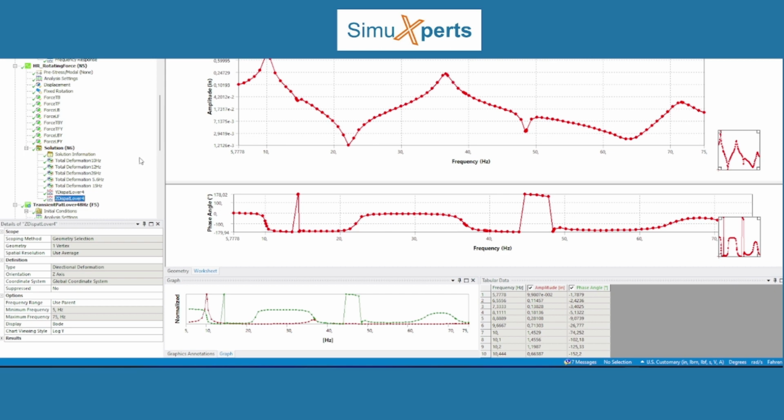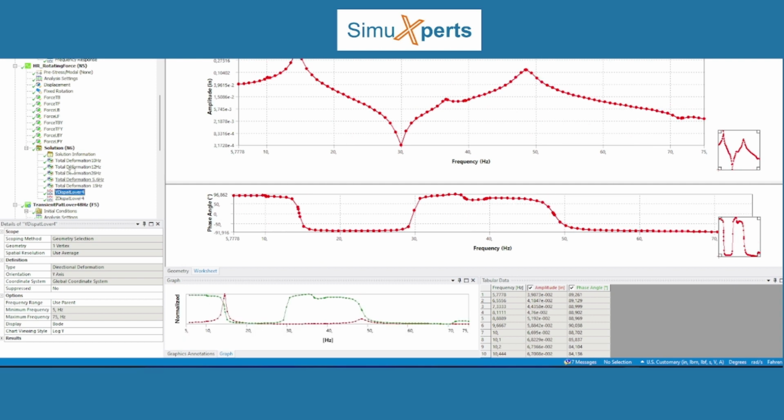Now, if we look at the other direction, the vertical direction, the response is at around 14 Hertz, which you will remember is the first bending mode around the strong axis, as well as around 48 Hertz, which is the second bending mode around the strong axis. And we see that these maxima are well represented in our curve.